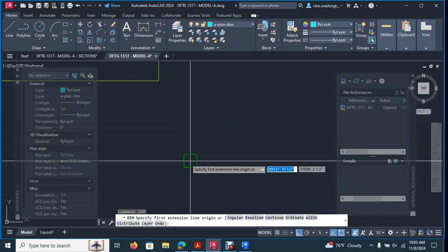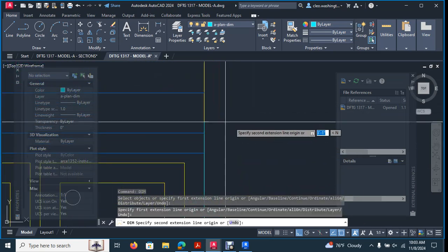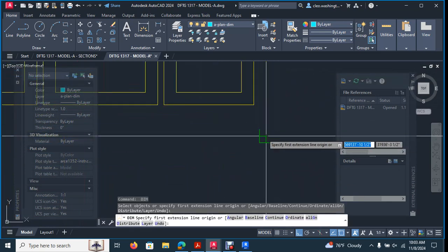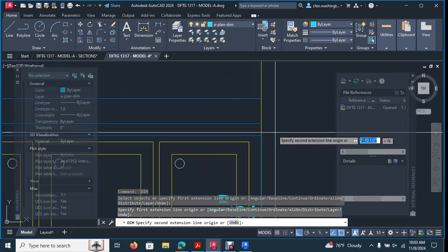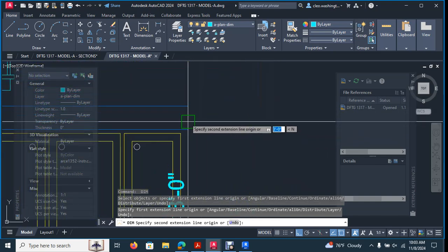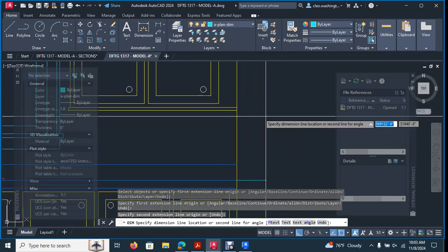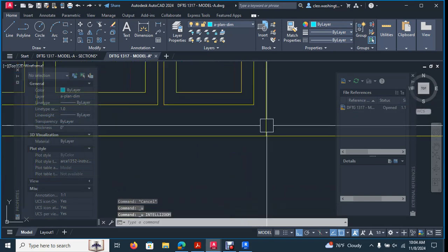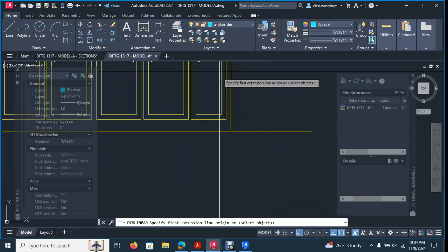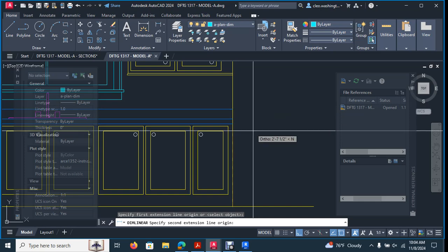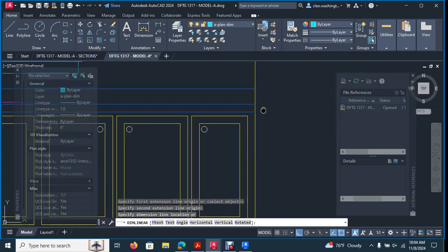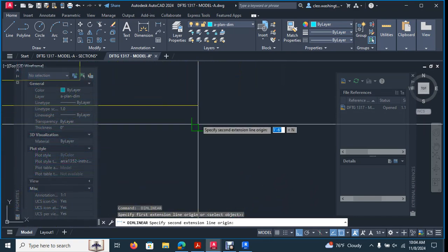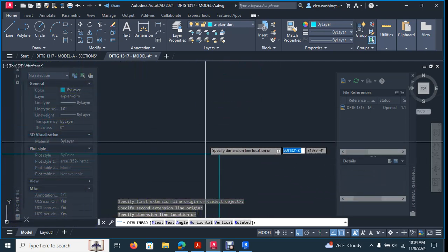So you want to actually drop one here. You want to go to the top of the counter. Not there, but here. Okay, then you want to add another one here. Oh, I forgot AutoCAD doesn't work like Revit. Let's go ahead and dimension. I'm going to go to here. Click and drag it out. Okay, same thing. You want to go from here to here to tell the contractor we have that 1'6".